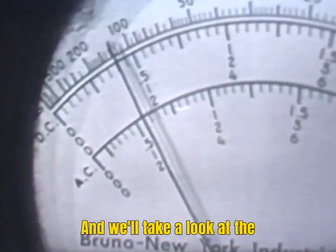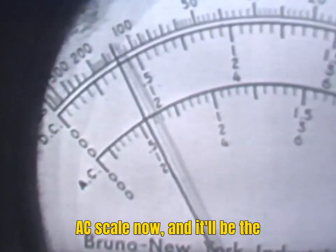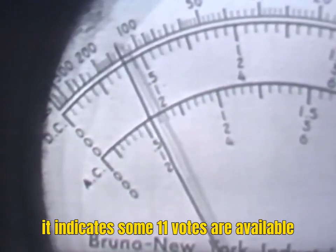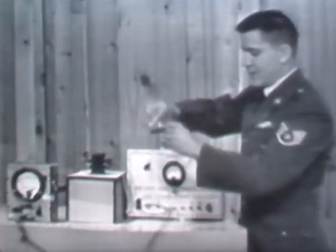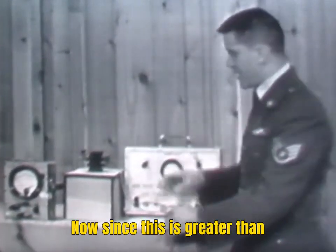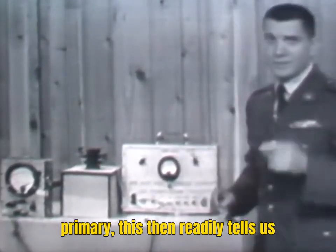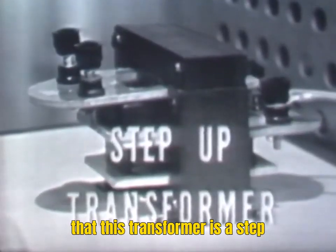If we take a look at the AC scale now, the middle row of numbers, you can see it indicates 11 volts are available at the secondary. Since this is greater than the 6.3 volts applied to the primary, this readily tells us that this transformer is a step-up transformer.